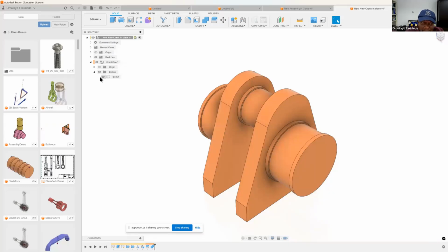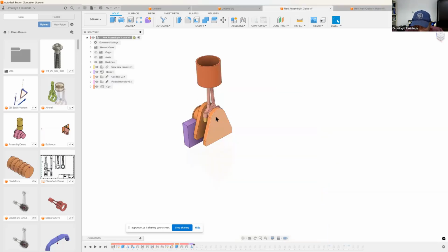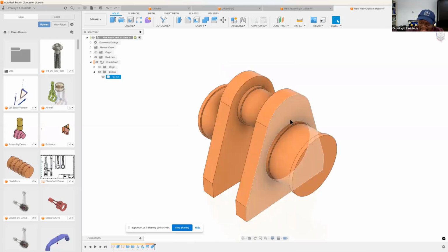Okay, so when we start, everything in this crank is a single body. If everything here is a single body, you cannot just come and remove this, because it's part of it. If you want to do a pattern replication and you have something here, then it will be on top of each other, because you need to remove this, since this is the period of the engine without that other rotor. So how do we do that? We do that by turning this single body into two bodies.